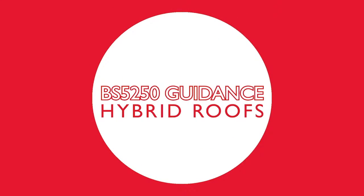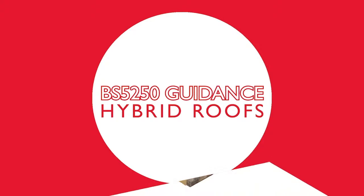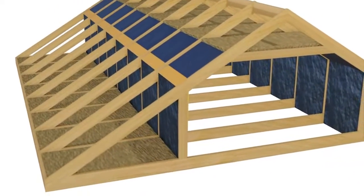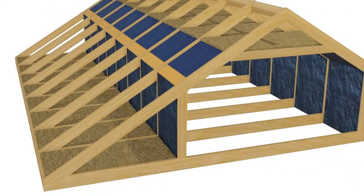Hybrid roofs. This type of roof construction combines both warm and cold roof elements and is sometimes referred to as room-in-the-roof construction. In this type of roof, there is a mix of cold roof voids, usually at the eaves and ridge, with a section of inclined insulation, sometimes called coombs, in between. Because of the different hygrothermal characteristics of warm and cold roof constructions, this type of roof poses some specific challenges.